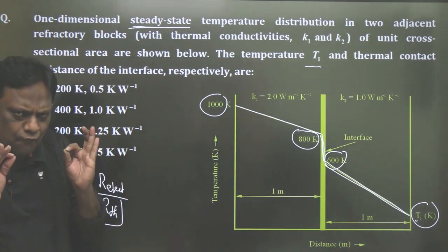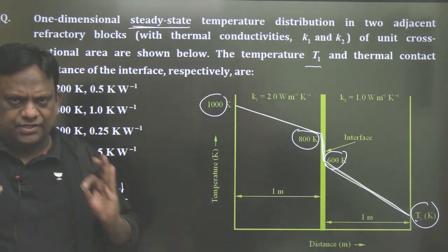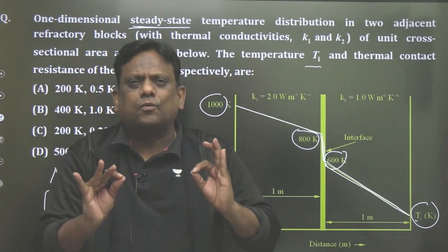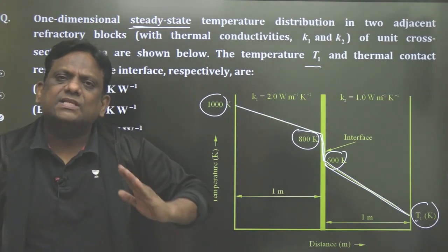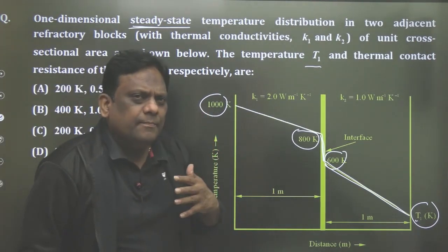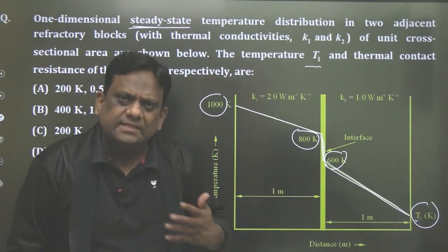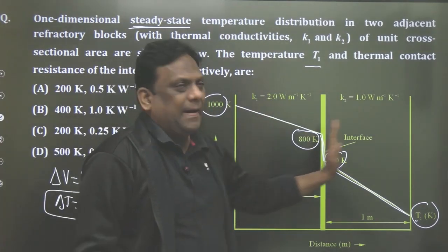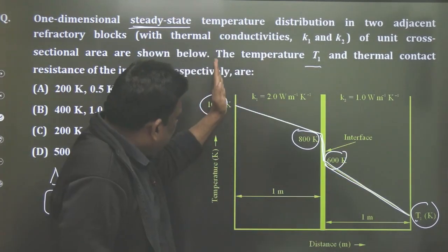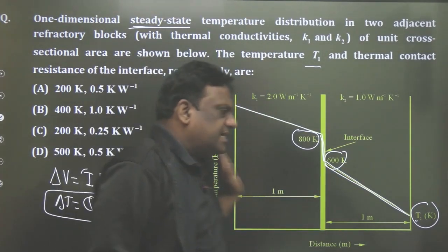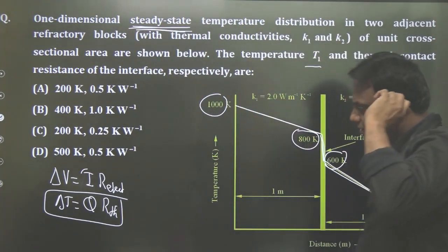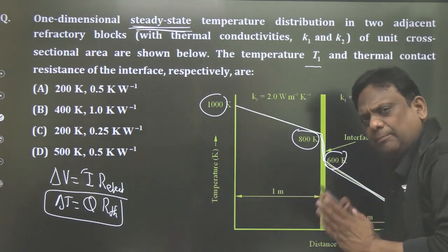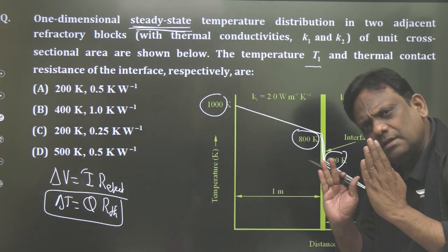Wonderful. So whenever you come across such questions, the first and foremost thing is to calculate the heat transfer. Why are we calculating heat transfer? Because that will help us calculate different parameters. How? Once I calculate heat transfer, at every section the heat transfer will be the same because it is steady state. So you can apply it to any section.